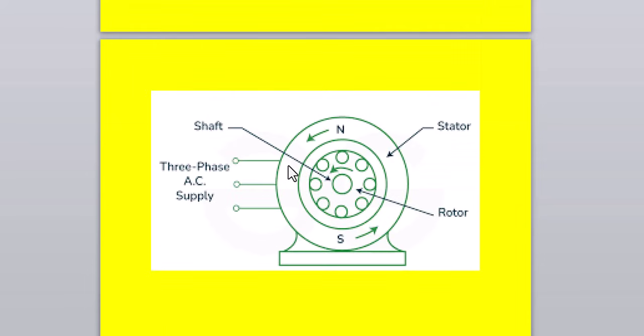In the stator we find the stator core loss, because the stator is made of laminations, and the stator also carries conductors, so there are copper losses associated with that. Similarly, in the rotor there are copper conductors, so there is a copper loss.